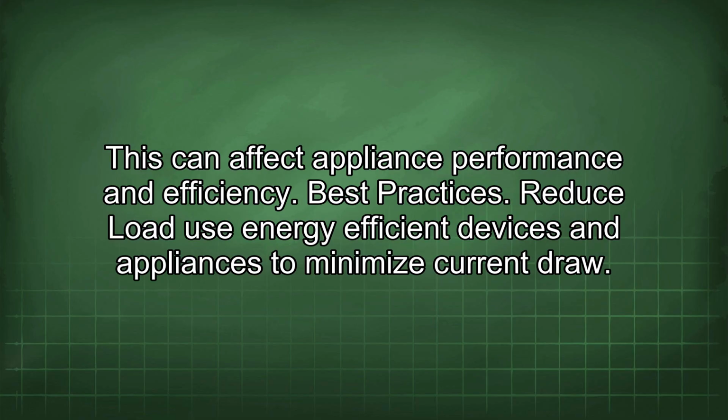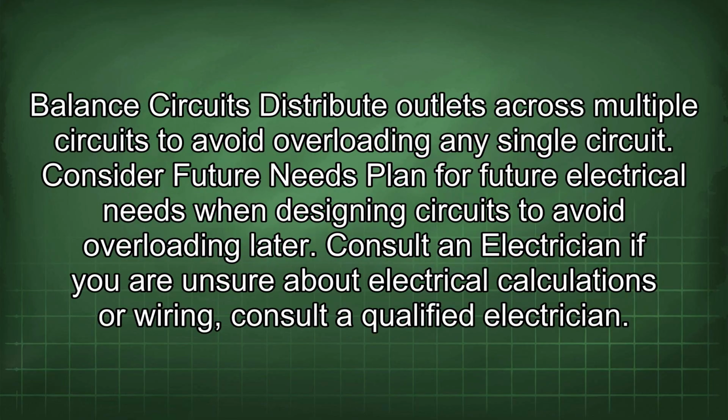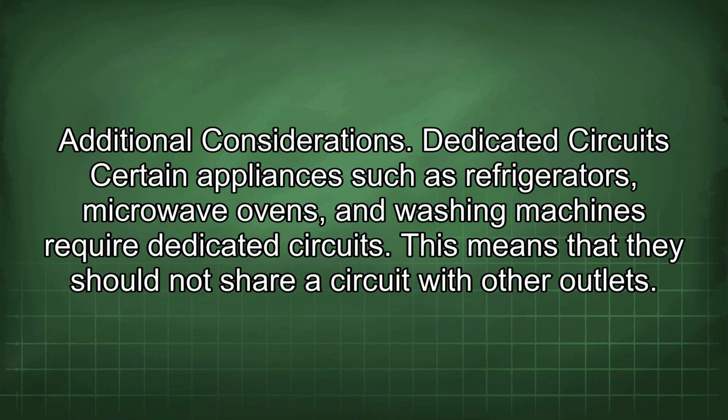Best practices. Reduce load. Use energy-efficient devices and appliances to minimize current draw. Balance circuits. Distribute outlets across multiple circuits to avoid overloading any single circuit. Consider future needs. Plan for future electrical needs when designing circuits to avoid overloading later. Consult an electrician if you are unsure about electrical calculations or wiring. Consult a qualified electrician.